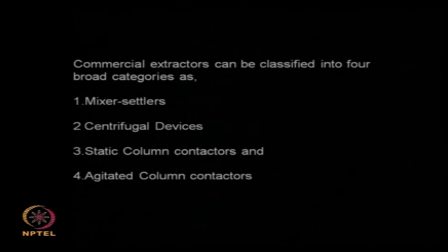Commercially, there are many types of extractors that are used. One is the mixer settler. A mixer settler is nothing but you mix your solvent with the feed using mechanical agitation and then allow the layers to separate out under gravity. That is called a mixer settler.